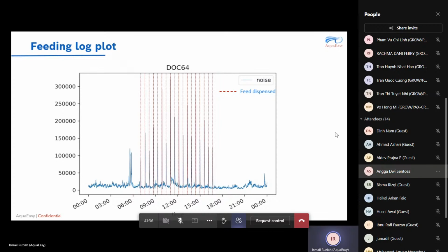Yeah, currently we only use DO. When we have a sensor in the water, typically we are able to read the DO, and therefore we can put a threshold on the DO so that we can stop feeding when it drops below certain levels.